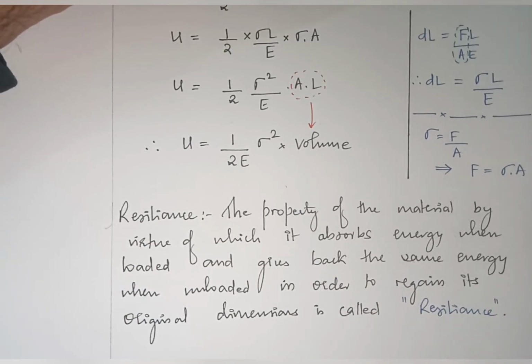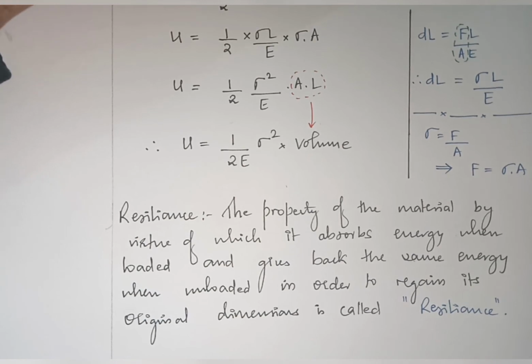Right, that's it. That is the property of a material by virtue of which it absorbs energy when loaded. Whenever you load it, it will store energy. As soon as you remove the external load, it will regain its original shape. So this is a property of all materials, any XYZ material you take up. That property we call resilience.